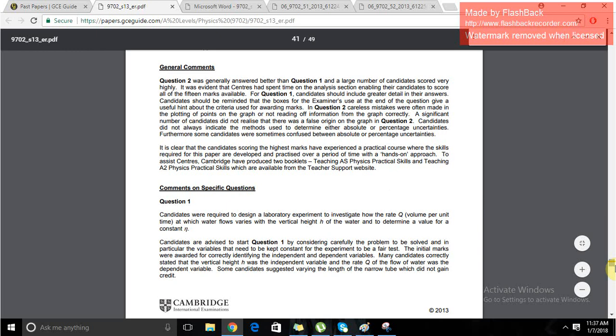And whenever there is measurement of something like d, such as an internal diameter, repetitive measurement at different orientations is a must, because often this thing isn't as uniform as you want it to be, and so you want to get an average of it, because that would be more true to the calculation you will use it in.